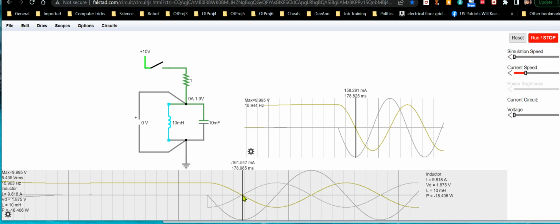The inductor is generating zero voltage now because, just for a split second, you can think of it as having no energy left in it, so it can't generate anything. However, like I said earlier, an inductor, even sitting at 0 amps, doesn't want its current to change. If it's got zero current through it, it wants to keep it that way.